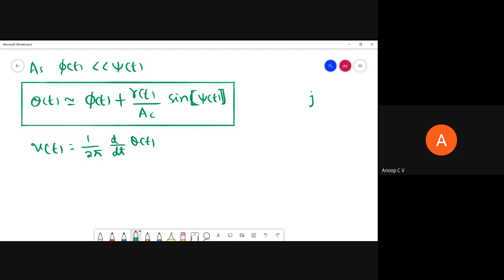We have studied the slope circuit. It is supposed to give amplitude variation corresponding to instantaneous frequency, so the output amplitude should be proportional to the input frequency, and it's a purely imaginary function. So it was j 2 pi f, right? This was the transfer function.